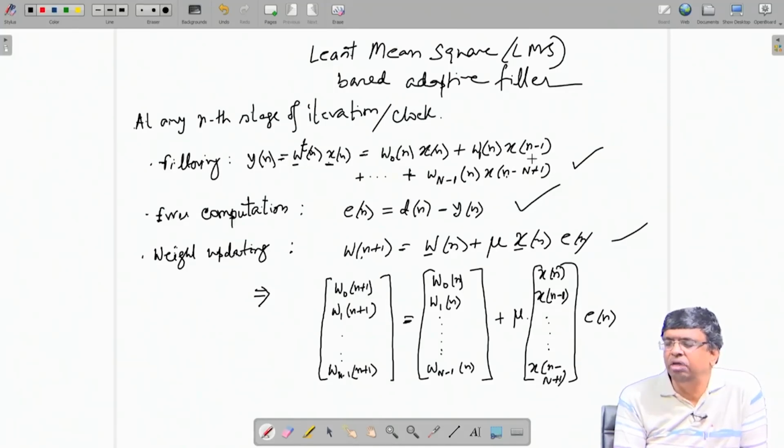For this, you have to proceed like FIR filter. You have to assume that these coefficients W0 n, W1 n, all these are known, they are available. Next step will be subtract this output yn from dn. Then is the most important step, using En and the given xn vector, calculate new weights, each coefficient. See, all the coefficients are used here, W0 n used here, W1 n used here.